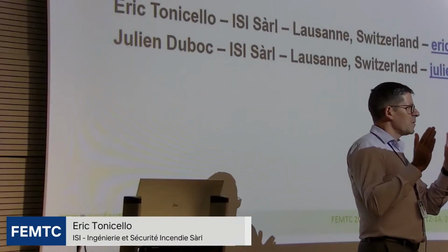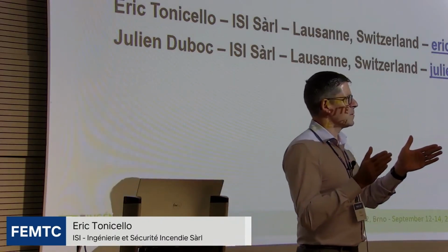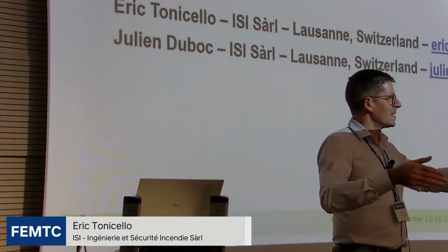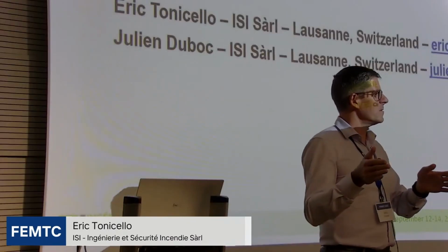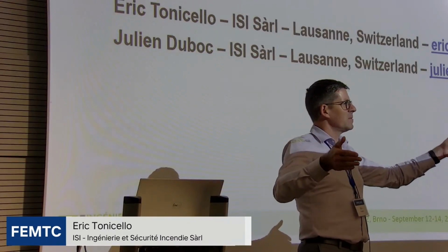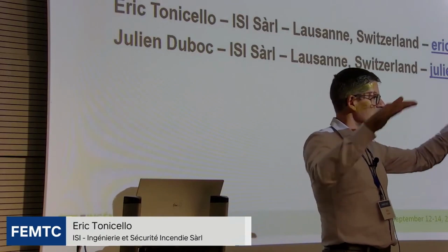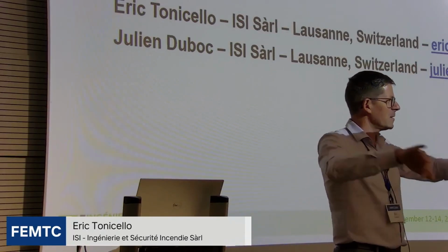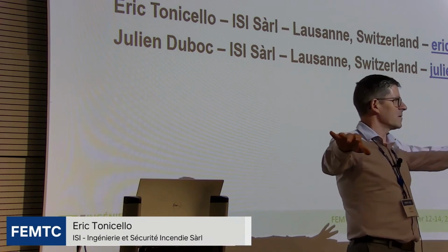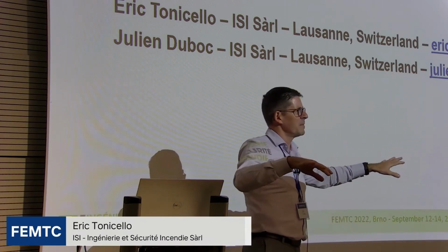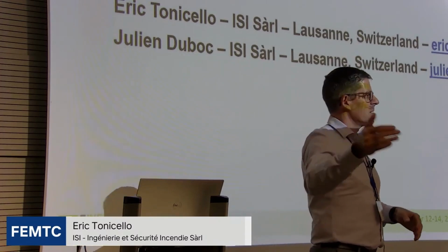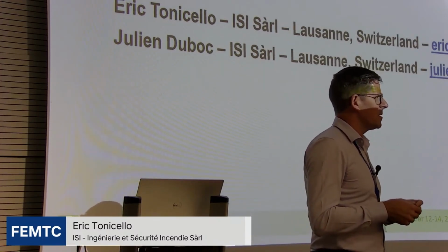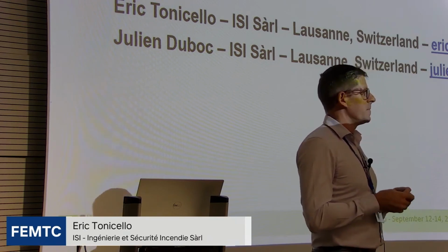So as I said, only a small portion of the tunnel will be with water mist. So if the truck is 15 meters and will be in between 2 or 3 sections, we will have maximum 45 to 60 meters with water mist. So people will not stay in the fire, and the water mist will go very fast on the side. So we think this is not a problem. The visibility has been checked by the other engineer. That will be okay. Okay, thank you.